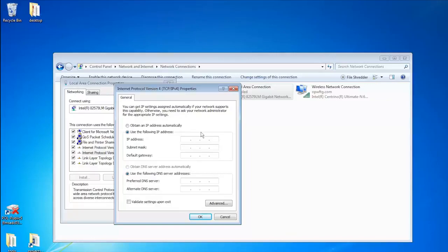of the Nano. The factory default for the Nano is 192.168.1.111, and since our laptop needs to be one off from that, we could set our laptop at 110. Then in our subnet mask, if we would just go ahead and leave that populated at 255.255.255.0, that would be fine. And since we're using a direct connection, you do not need to worry about putting in a default gateway.